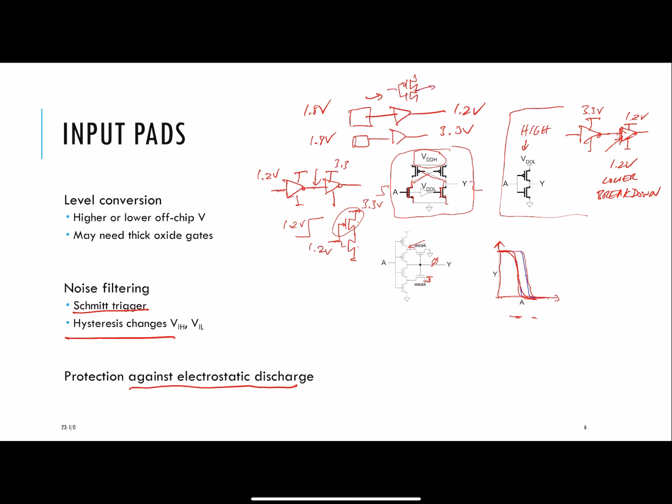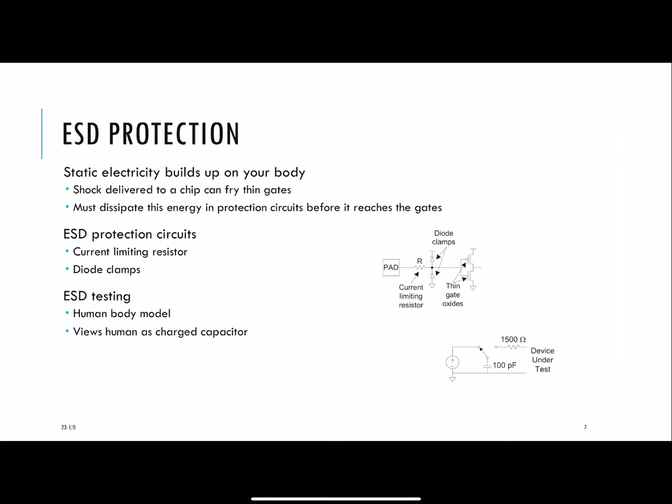By itself, there's nothing. If you dump like 2,000 volts there, it'll just kind of sit there. It'll do charge sharing. So it might go down a little bit depending on what the capacitance that's creating the electrostatic discharge is, versus the value of your gate. But you'll blow that sucker up. So you need to find some other protection against electrostatic discharge, specifically on the input devices. And we'll talk about that. Well, I guess we talked about it immediately.